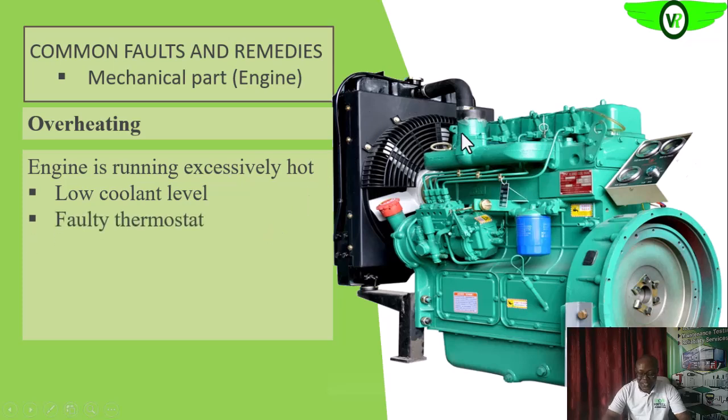Then faulty thermostat. Remember, the thermostat is here. If the thermostat is not opening when it is expected to open, it means that the engine will run hot. Are you getting it? Because the cooling water is not flowing through to the radiator. So if the thermostat is faulty, we can change that thermostat.